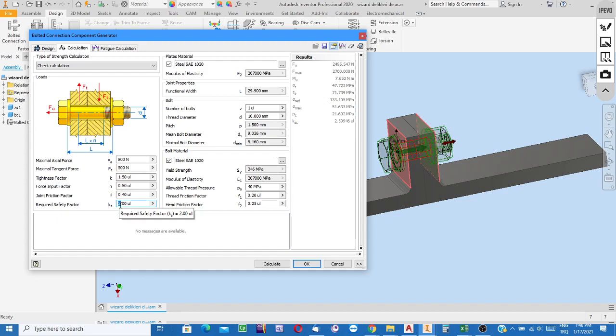So it's a factor of safety in such a case. If you're not so sure of the quality of the production, then to be on the safe side we use a safety factor. Well, here factor of safety for this bolt nut joint, let's say 3 times safe. I want to have the joint as 3 times safer than the ones mentioned in the declaration form of this product.